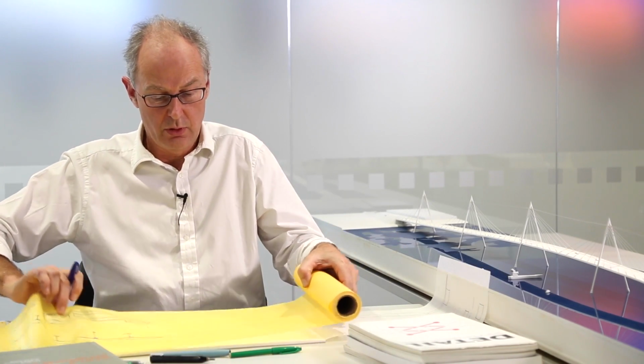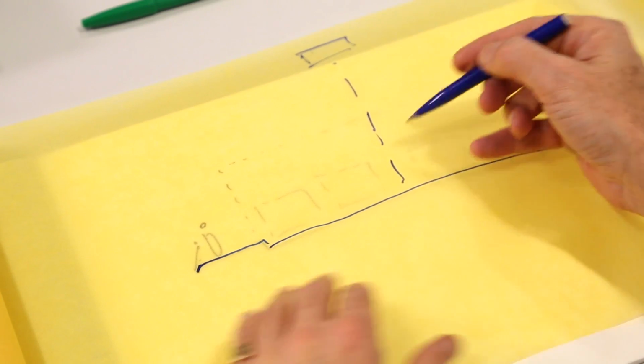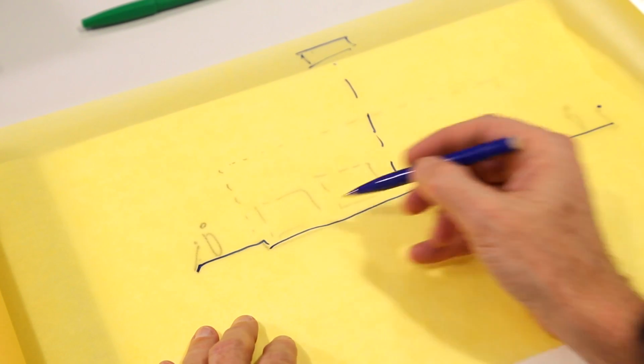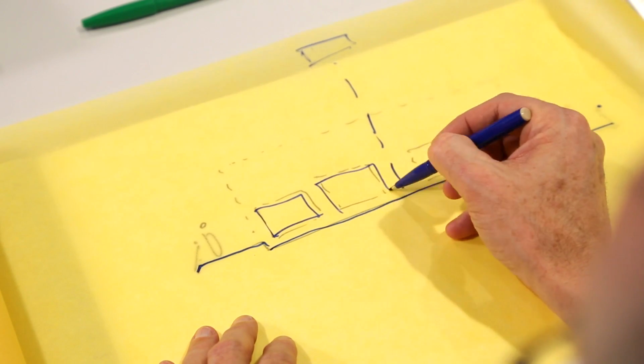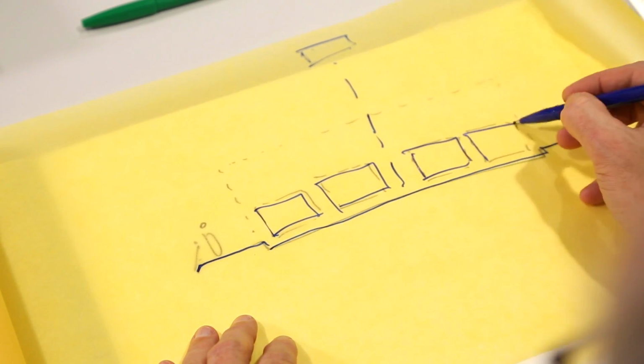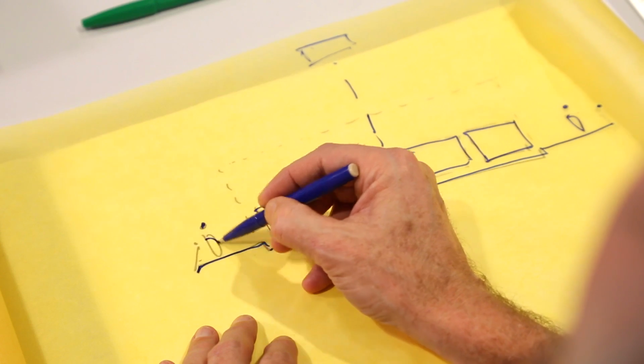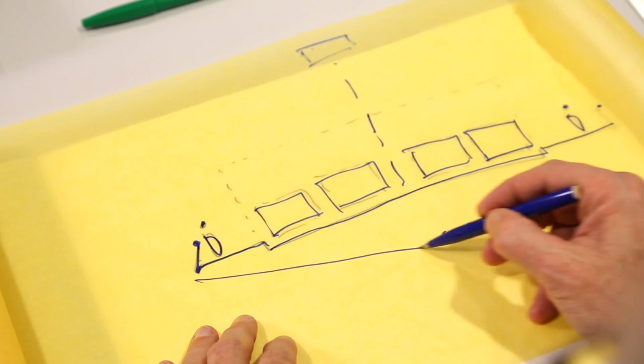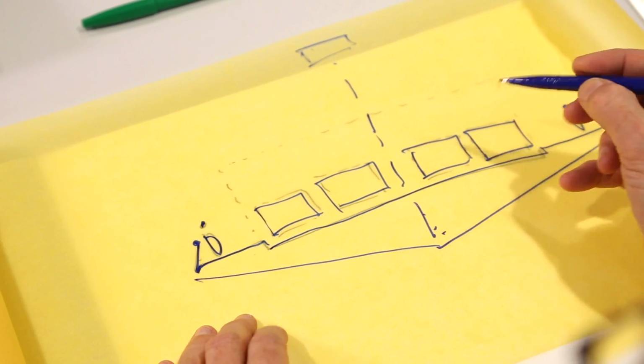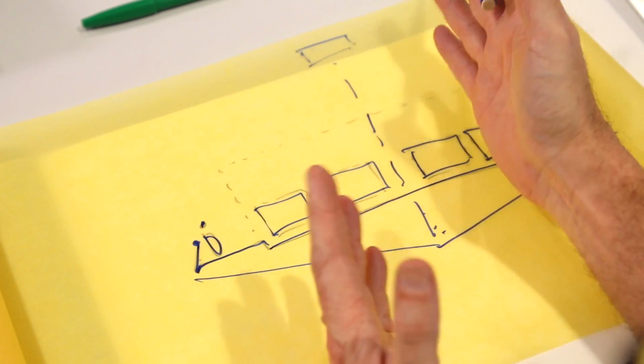So another way of doing it, perhaps going back to the arch solution, would be to have structure over your head. That would still have the same functional cross-section, we're still having to carry the same things, but now you've got to think about where the structure is going to go overhead. One option would be to put the structure on the centre line. If you do that, you're going to need torsional stiffness so that the thing doesn't twist under eccentric load, so we're going to have to make this into a box structure. That's fine. That is one kind of structure.